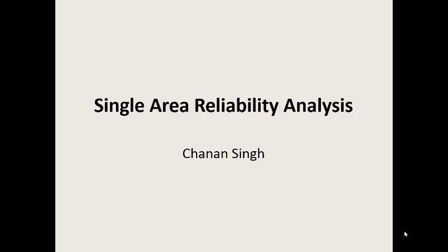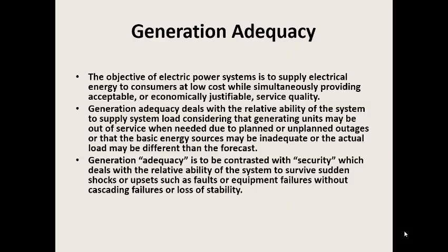One is the single area, the other is the multi-area. In the single area, all that we are interested in is to consider the adequacy of generation to supply the load. And we assume that the transmission capacities are adequate to carry the generation from generating points to the load points.